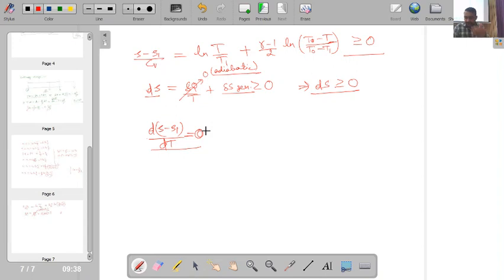Or, let me pose it in another way. This is one important equation which relates the temperature and entropy. Now if S minus S1 you call delta s, it is relating your temperature and delta s. If you take this equation and plot it on temperature and delta s axes, you will find this equation gives you a curve something like this.